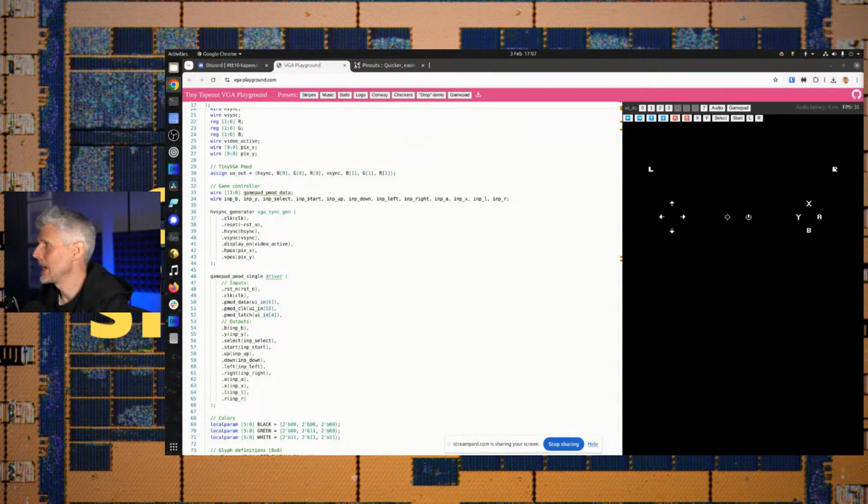So onto the main part of today's stream. We had an interesting question coming through the Zero to ASIC course from someone who wants to see what happens as they lower the supply voltage of a digital design. And you might think that that's easy to do. You can just turn down the supply voltage, VCore, and that would work. But that doesn't work because your design isn't the only design inside Tiny Tapeout. Your design is one of many designs.